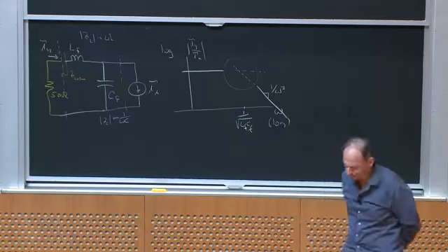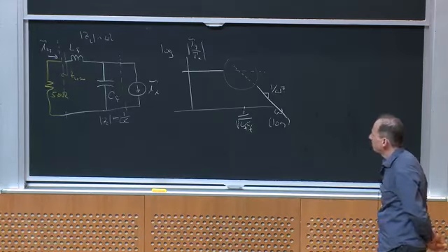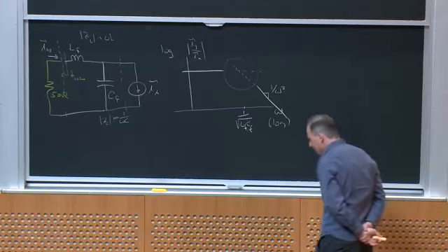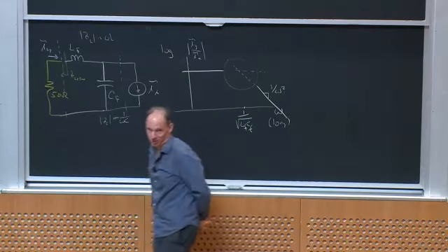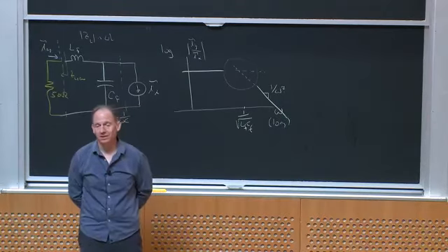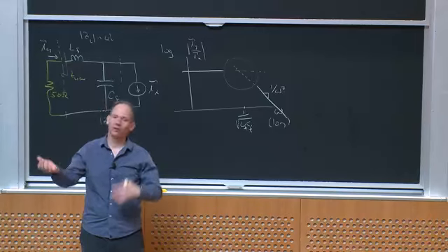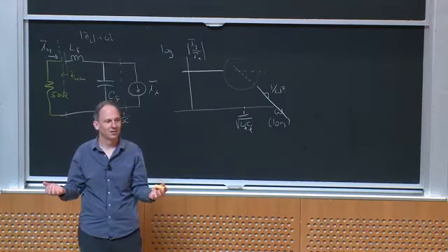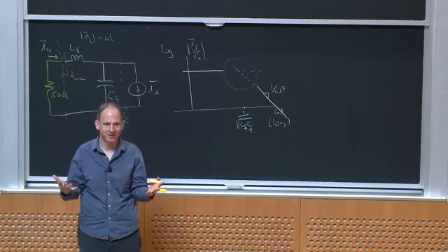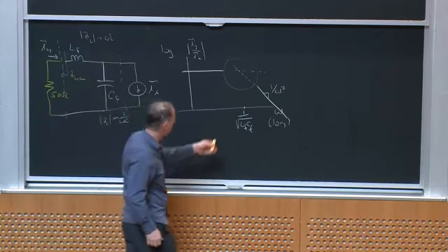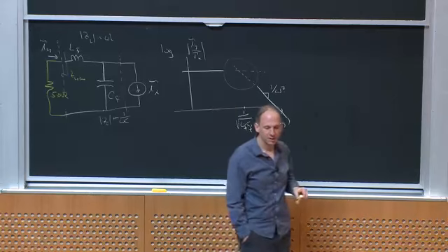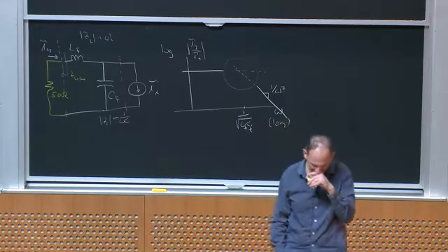Okay, so I want to build this filter, okay? And as I said, I need a lot of attenuation. If I'm going from 100 amps to 100 microamps, that's 6 orders of attenuation, right? So I'm probably going to need a pretty low cutoff filter here. I'm going to need a bunch of attenuation.